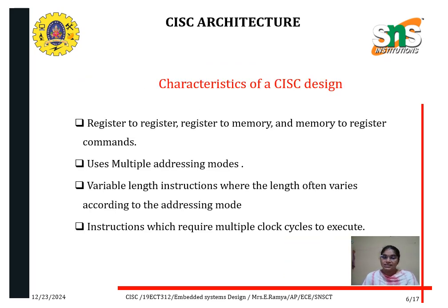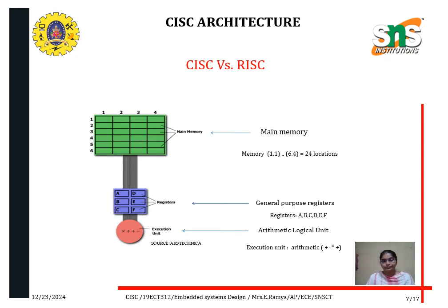What are the characteristics of CISC design? Register to register, register to memory, and memory to register. Use multiple addressing modes, and variable length instructions where the length often varies according to the addressing mode. Instructions which require multiple clock cycles to execute.